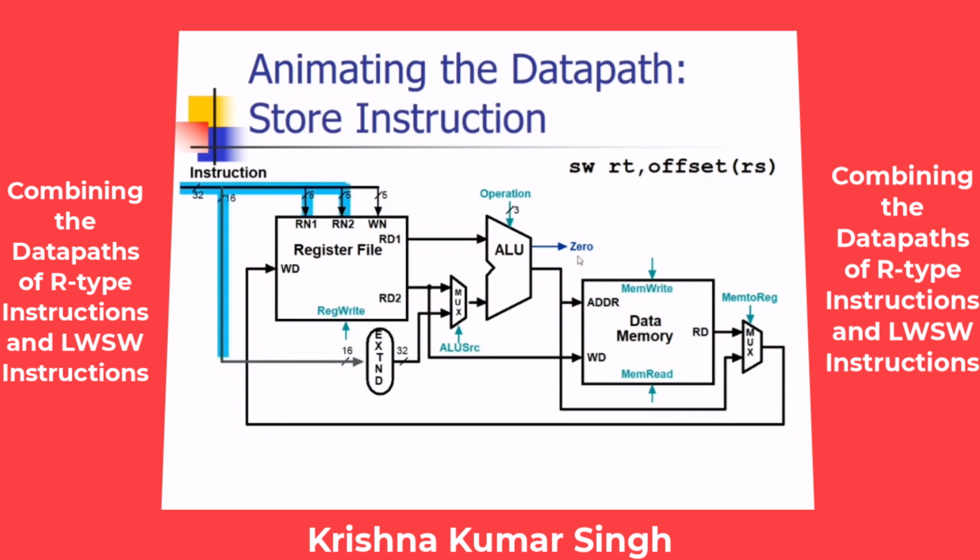For the store word instruction, these are the parts of the data path that will be used. We find the address of the memory location that we are going to store this register in by using the ALU, and this multiplexer should be, again, 1, because we are going to select this part of the data path and give it to the ALU.